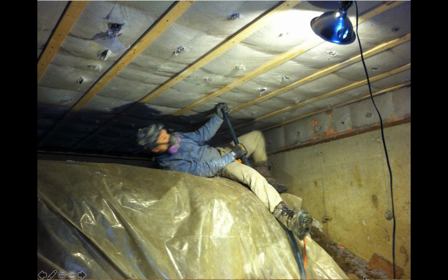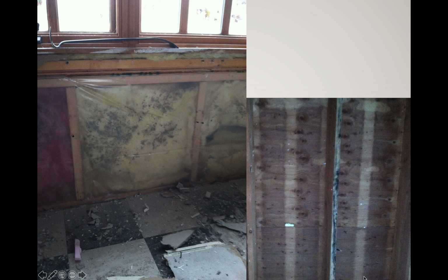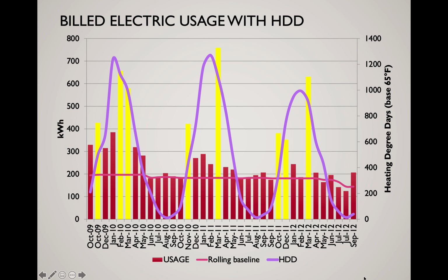In this case, this is me insulating that floor, which then, again, with a friend, we finished insulating it with continuous insulation. When I went to gut the interior of that, I found a whole lot of mold. And you will see that vapor barriers applied in the wrong place, or vapor barriers at all where there ought not to be a vapor barrier, can result in moisture accumulation, which results in mold, which can be quite hazardous to people's health living in these buildings. And you'll find that in these newer buildings with much more vulnerable materials, that's an increasing problem.